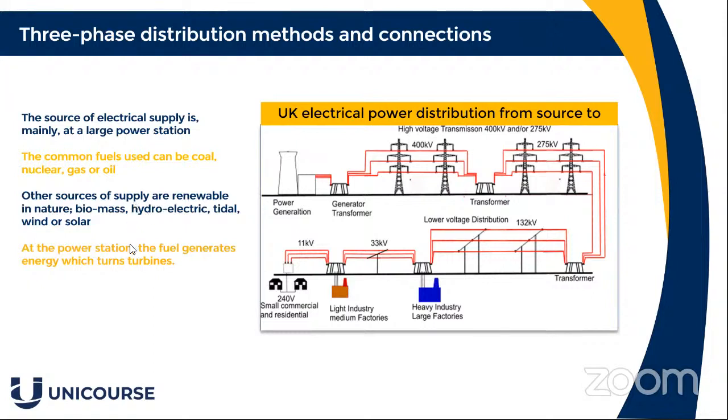These are what we use to power the turbines, and they are dotted around the UK. Ideally I think we're looking for fewer power stations, especially if they're going to be using things like nuclear, which is growing at the moment. These turbines quite often will generate around 33 kilovolts, and that is the reason why we have to step them up, because there will be a volt drop on these lines, and when they eventually get back down to the transformer, we've still got high voltage.